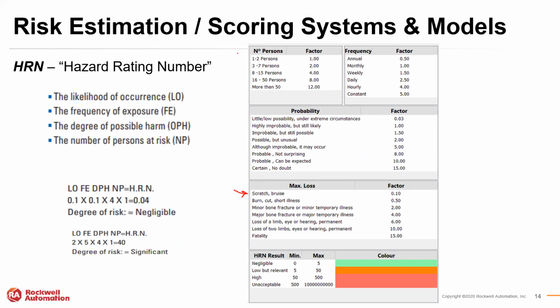And then this also includes number of people. With machine safety, we're most typically worried about one or maybe two people at a time. Some machines, more complex, bigger lines, we might have more people involved. But that's one of the bigger differences of machine safety and process safety. Machine safety, we're thinking about a couple of people, an operator, a maintenance person, quality engineer, whoever is involved temporarily, maybe exposed to that machine, as opposed to process safety, where we're concerned about many people or maybe an entire community and different exposure rates.